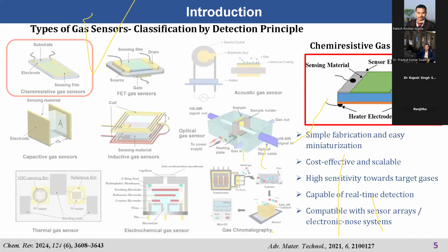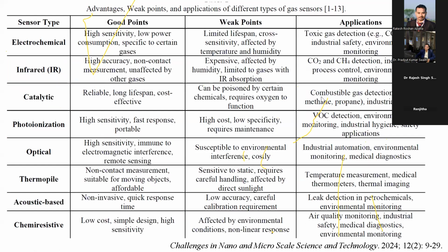Okay, so if you see the resistive gas sensor, it will essentially have two electrodes and the sensing material in between. In some cases there will be a heater at the bottom to control the sensor temperature. So for all my devices, this is the typical geometry I will be using. Sometimes some complicated electrodes or heaters are made, but principle-wise it is essentially following this.